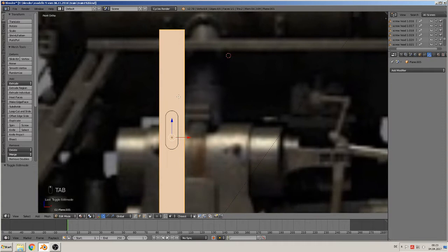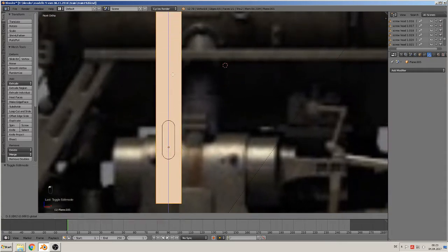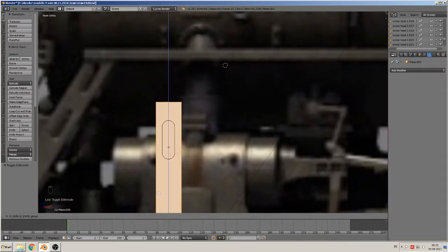Be sure that you are in front of the object we want to cut. So at first we take the main object, then the second object, then we go in edit mode, A to select all, and then knife project. So we cut it in there, a nice hole. We must do it again, I think. Good. So we do it again.